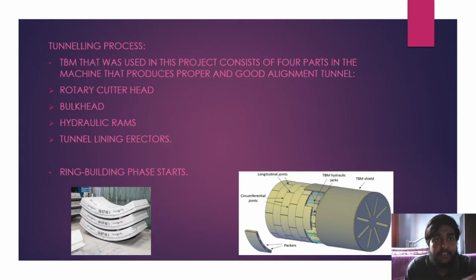And now, after the drilling process is over, the ring building phase starts. A complete tunnel ring consists of several lining segments made of pre-reinforced concrete. These are made in a special factory above the ground. They must be matched to the exact size required and are taken into the tunnel on flatbed rail cars. The concrete segments are fed by the concrete feeder and lifted into place using a vacuum.